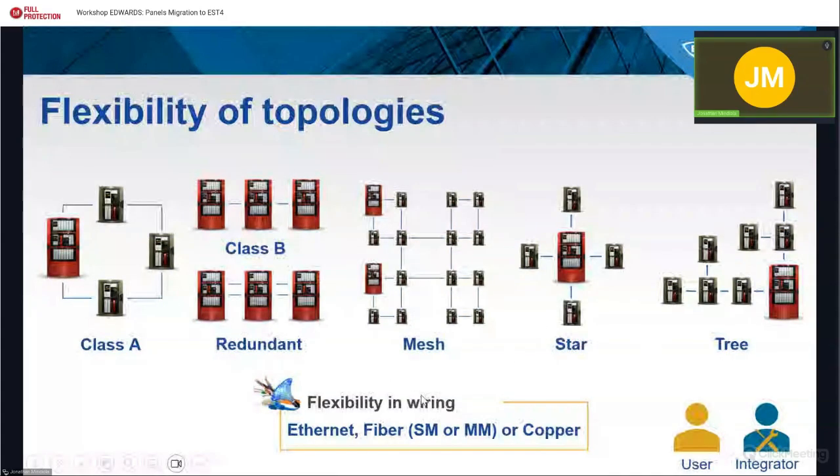And you can reuse the same cable that you installed with the EST3. It is with the fiber in single mode or multi-mode, with the copper, and you can also have with the EST4 the Ethernet connection. Or in the case that you install an EST4 panel and you will be designing the project with this network, you'll be able to design the project with the Ethernet connection or fiber connection with single mode or multi-mode, or copper. We have these three options, this flexibility of the wiring between panels.